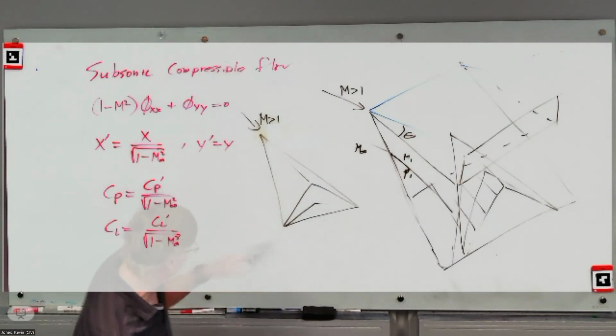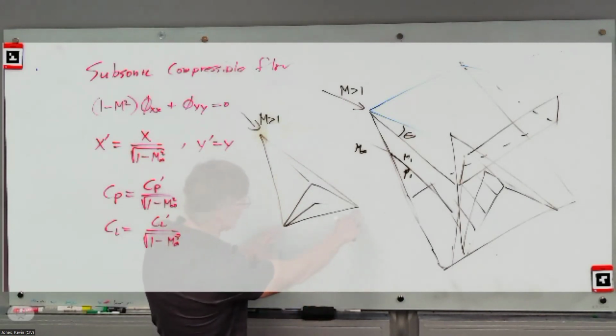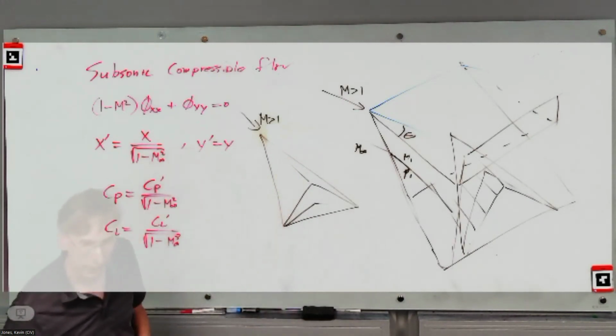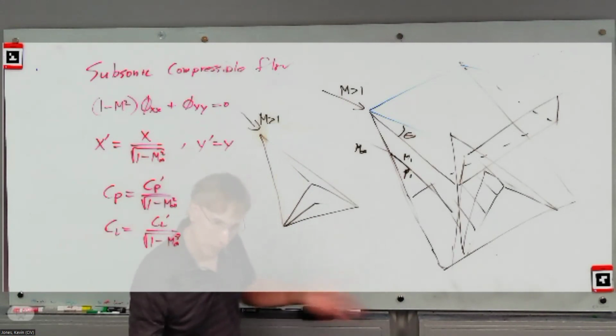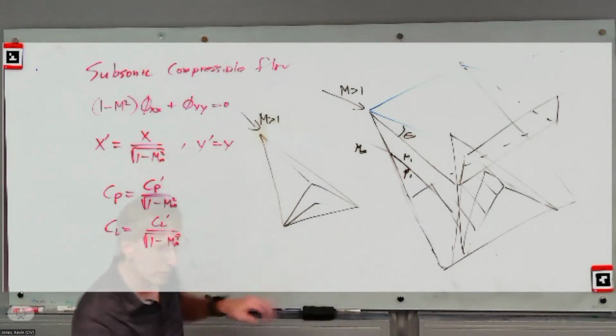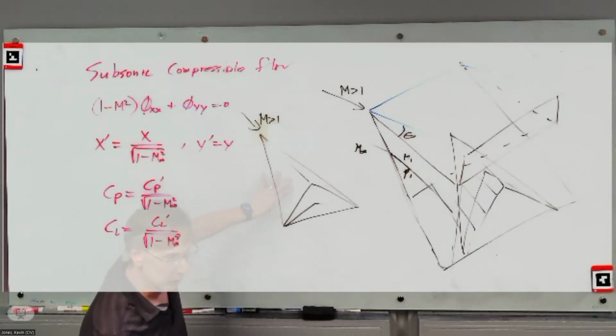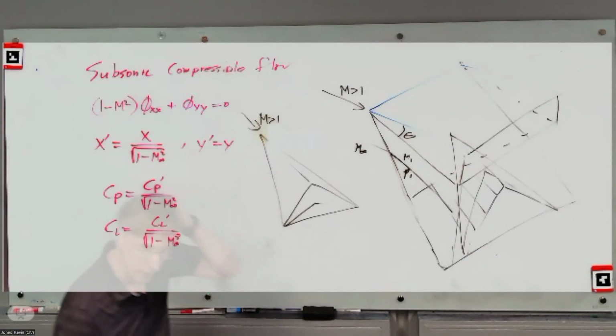I think everyone had this big idea because the shock touches the leading edge. That means there's no flow that spills around the leading edge. So kind of like we were just talking about the difference between subsonic and supersonic, tip vortices travel everywhere in subsonic flow. This would somehow isolate the two, so no pressure spillage. And they thought somehow that made the shape optimal in some way.